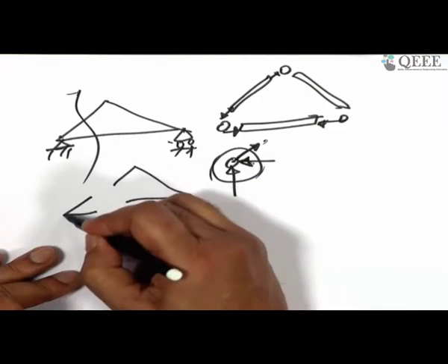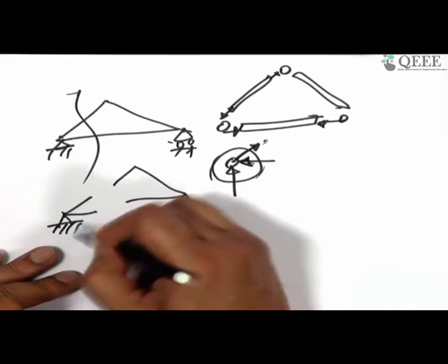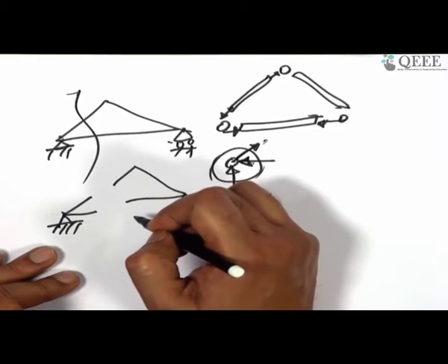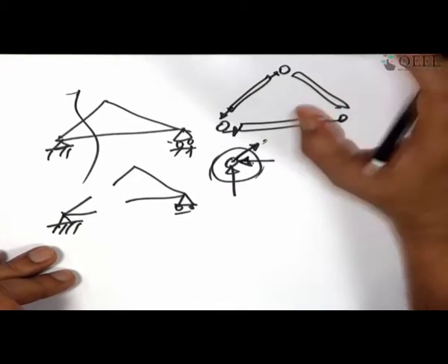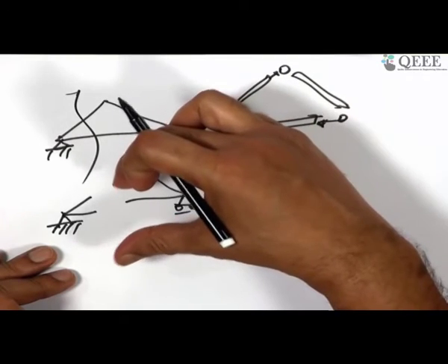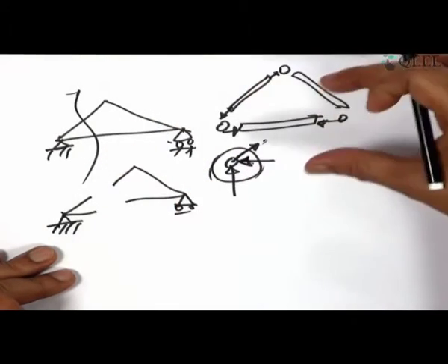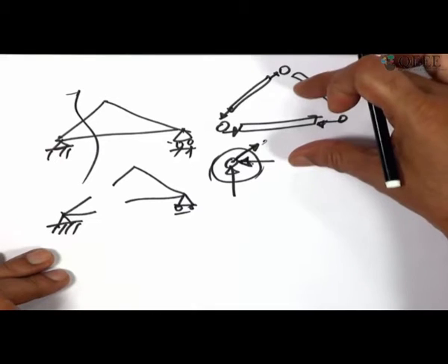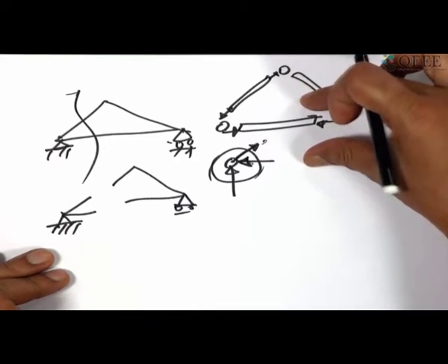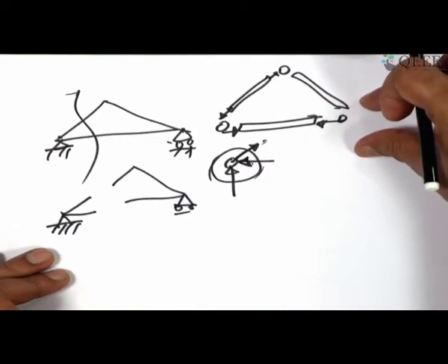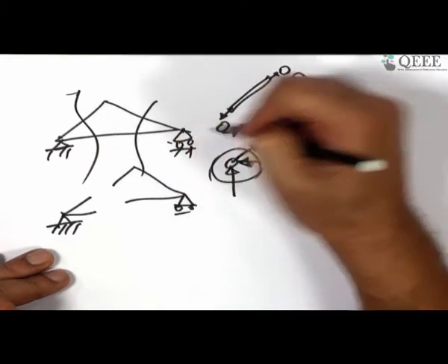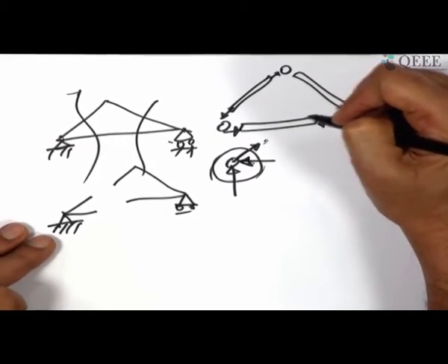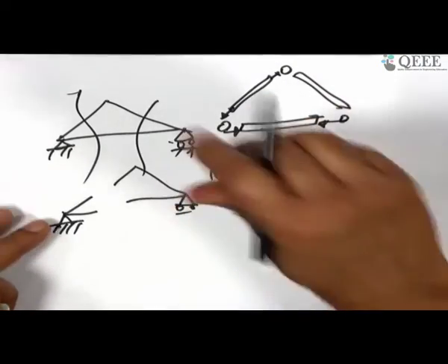So, these are the two rigid bodies, and you can solve by the method of sections considering the truss as a rigid body. You should not have any difficulty in the solution of a truss that we are treating as a rigid body while doing the method of sections, and pin connected parts, rigid parts, while dealing with the method of joints, and they are absolutely applicable. If you make several sections of the truss and separate out, both the methods effectively coincide with different assumptions. So, this is an out of the way discussion, we do not need them.